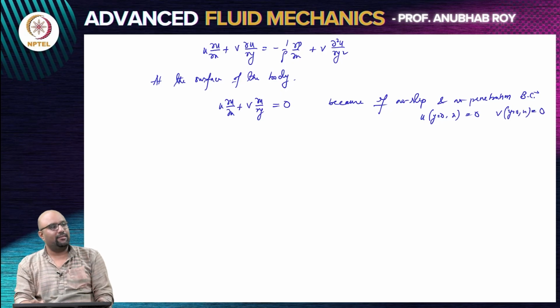So, in today's lecture, we will actually try to see what is going on near the surface, what is exactly happening near the surface, and what role pressure has to play regarding what we see towards the surface. And this brings us to what is probably theoretically the hardest, but from an application point of view, the most relevant question: when does the boundary layer stop remaining attached to the surface? Will the boundary layer forever remain close to the surface, or is there a possibility of the boundary layer getting detached from the surface?